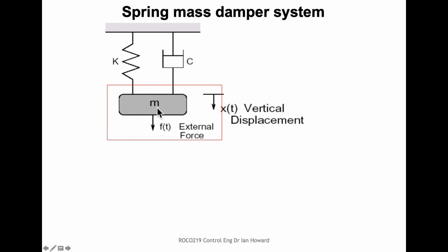But we can also see that if we try to pull down m, the spring constant is going to try to resist it, and the damping from the dashpot is also going to try to resist it. So if we pull down, the inertial mass is going to try to stop the system moving, and we know force equals ma. The spring is going to move away from its original condition and extend further. And with the dashpot, you're moving this viscous thing, which is also going to resist movement.